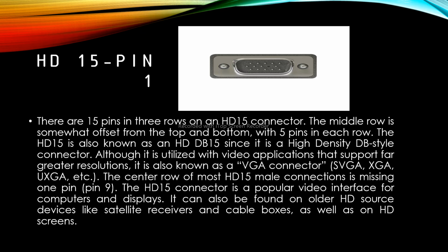HD15 pin. There are 15 pins in 3 rows on the HD15 connector. The middle row is somewhat offset from the top and bottom with 5 pins in each row. The HD15 is also known as an HD DB15 since it is a high density DB style connector. Although it is utilized with video applications that support far greater resolution, it is also known as a VGA connector, as in VGA, XGA, UXGA, etc.